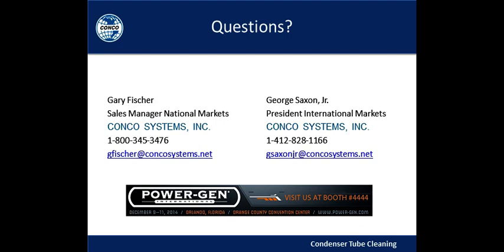Okay, this is Gary again. You can have that situation. We have trained crews that go out and inspect the tubes whenever they go in to do the cleaning. Typically, if we are able to get in there before the cleaning, we will have one of our technical sales staff go in and look at the fouling itself. In most instances, using the proper cleaner, you can remove all that fouling. But in some instances, calcium carbonate, if you allow it to build up to such an extent that it is too thick, then we can't even get a cleaner down the tube.